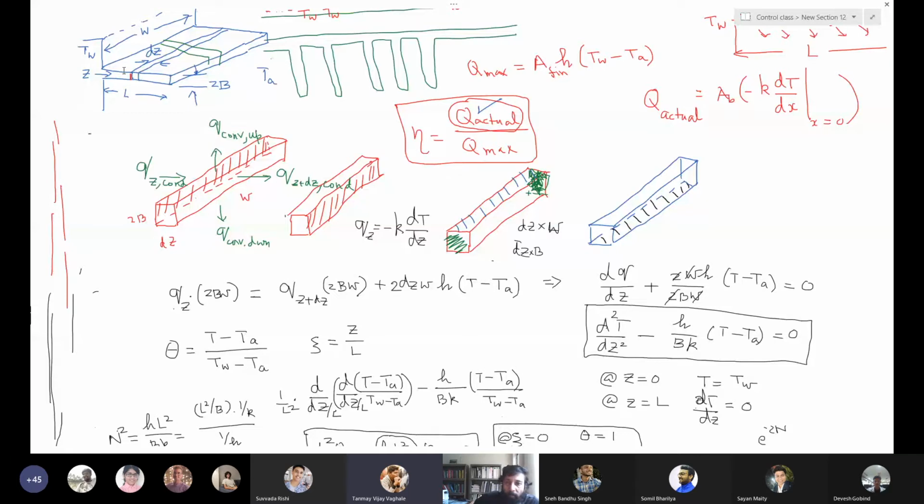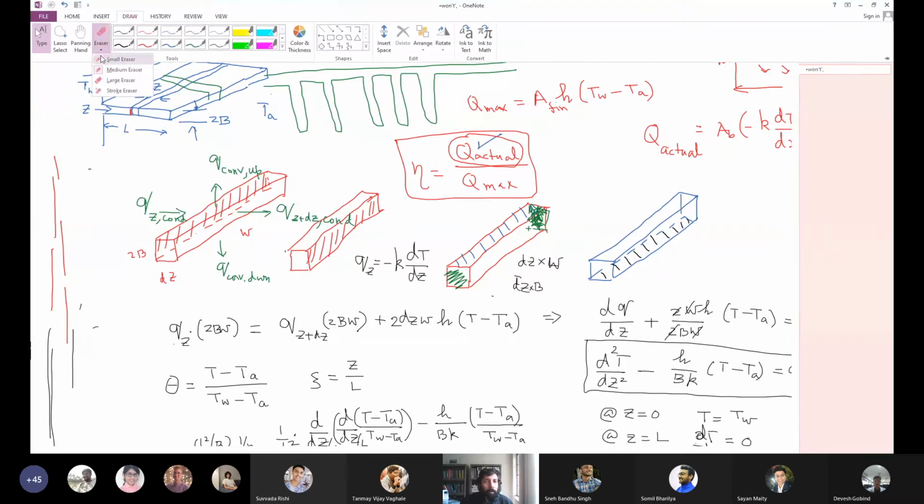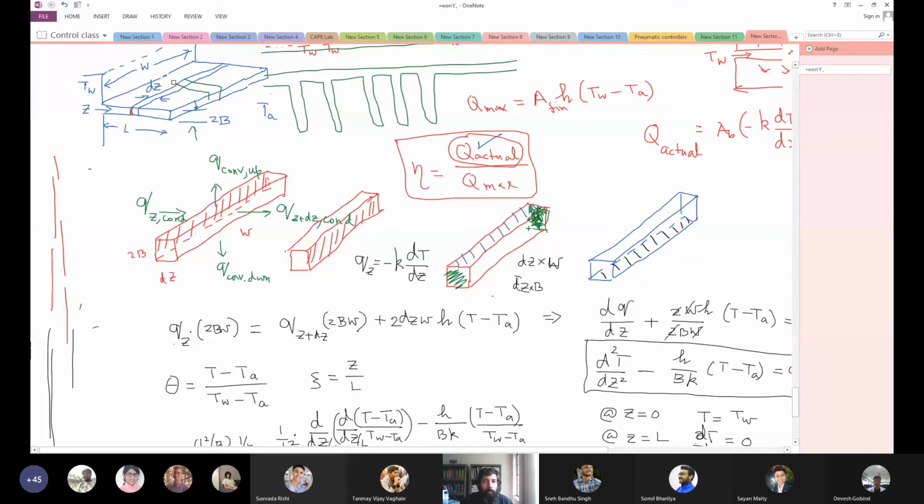Yeah. So one of the ways you can think of this total heat transfer is the total convective heat transfer, because T_A is known, T is known, and the convective heat transfer coefficient is known, but that will require an averaging over the entire fin surface. What I have heard in many classes before is to take this surface, take the heat transfer from any differential area and then integrate it over the entire surface. That in principle can be done, but that is much more cumbersome than recognizing the following.